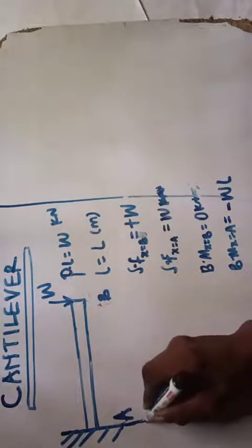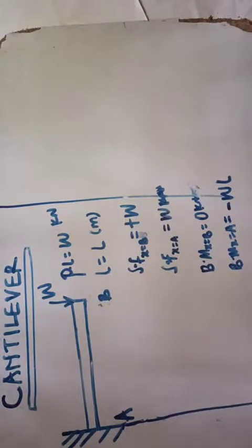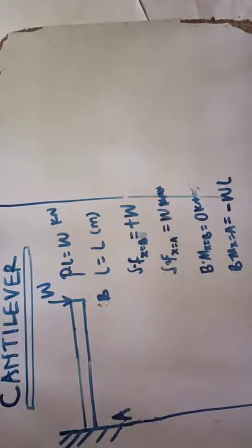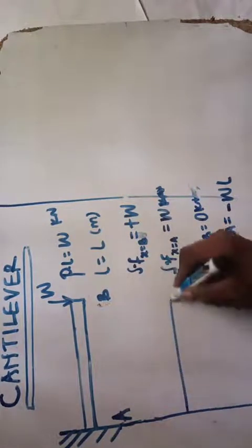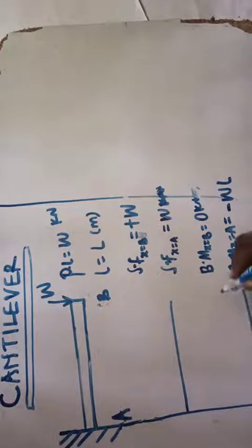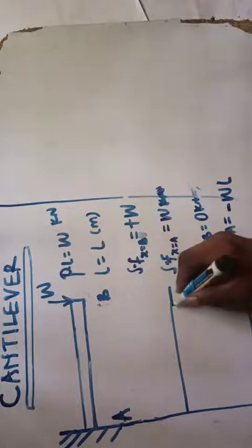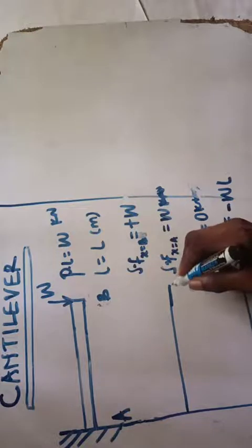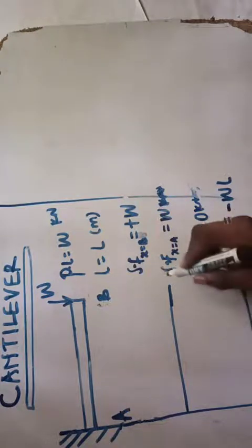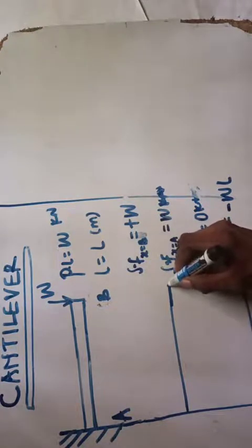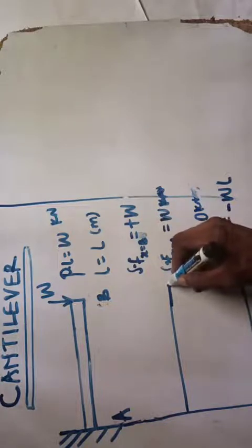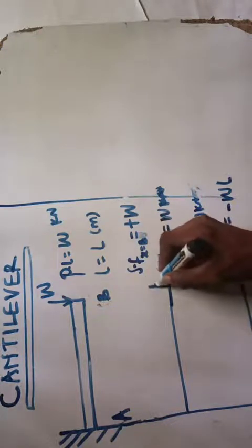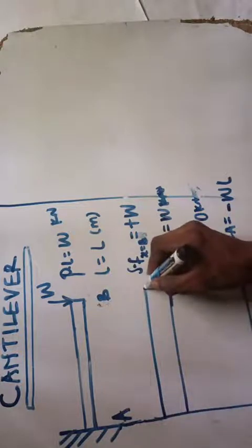And now you want to do your shear force diagram. You're going to have something like this, and once I have something like that, I put my shear force diagram here and my bending moment diagram here. So having got this as well, I just want to draw. At this point my shear force diagram is fixed. So at X equals A it is still W, right? So I measure my length W, and it's just a straight line because it's still the same thing throughout.